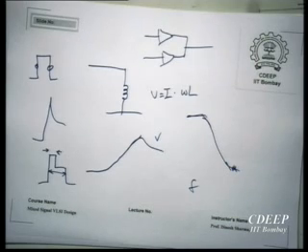Okay, so now that problem, that I have reached a critical length of the wire and I look down saying, okay, give me some space, I need some real estate here for a buffer, and find that there is no real estate available. Either I elbow aside some existing circuit, relay out, etc., or go to a non-optimal wire length and put the buffer there. That problem is not there. Simply look, no buffers. Just honest to God, transmitter at one end, receiver at the other end, and a plain wire between the two. So we are back to good old days when connections were connections and did not demand this. So I think that's a very big plus point for this.